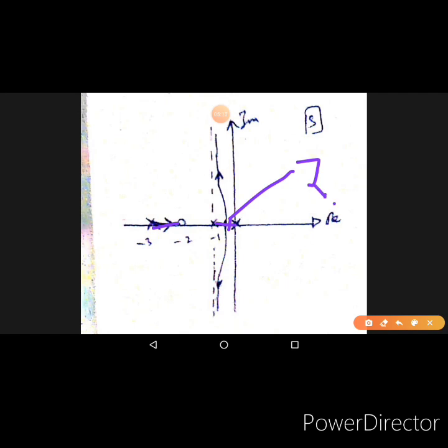One of the poles moves upward from the breakaway point and starts following this line towards infinity, and the other one towards minus infinity, and reaches the 0 at minus infinity. The other pole reaches the 0 at positive infinity. In this way we will have our root locus, which you can see over here. This is our final root locus, which we have drawn in this problem.